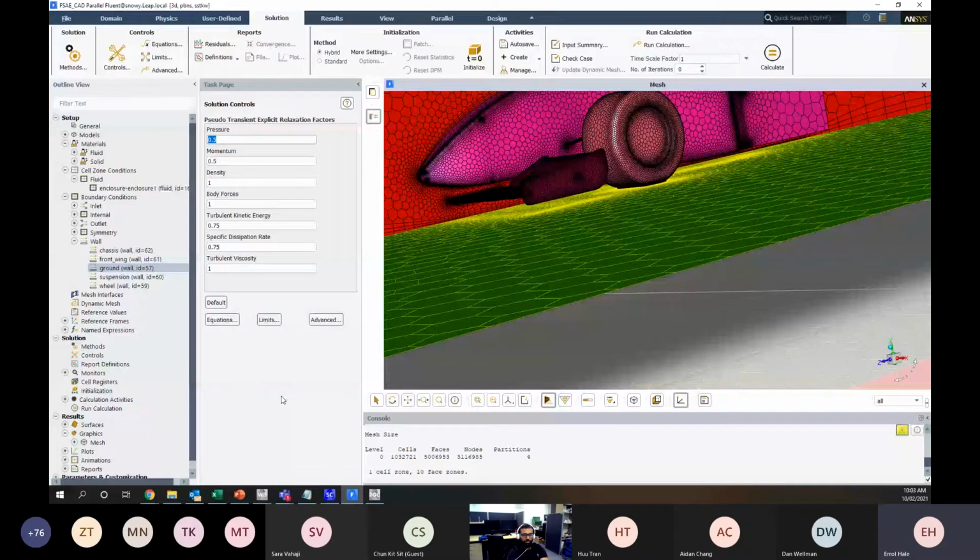Okay, so for our second iteration, we got P2, and that difference between P1 and P2 might be really large. And if we take that whole value for pressure 2, we might get oscillations and difficulty in convergence. So we use under relaxation factors to allow a solution to converge more easily where we're seeing that it is being unstable. Okay, so we can play around with these once we've run our solution and assessed the convergence behavior.